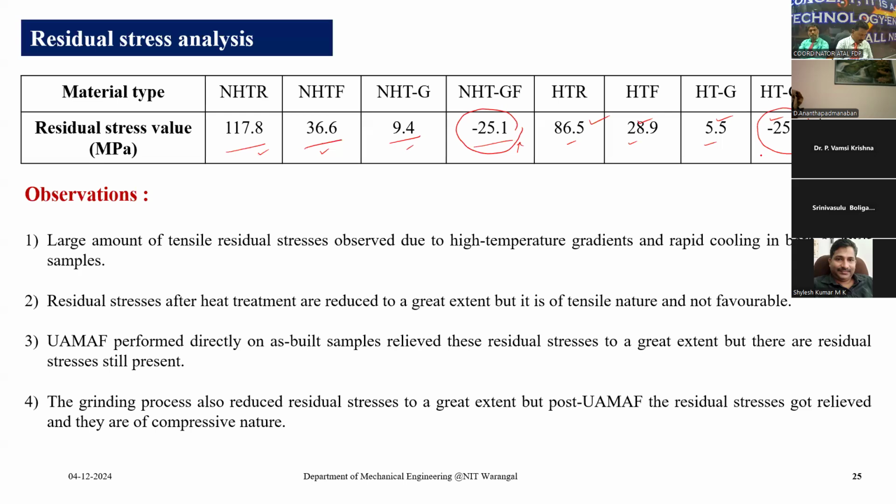Already I told you at the start itself, the tensile residual stresses observed are due to the high temperature gradients and also rapid cooling in the as-built samples, and the residual stresses after heat treatment are reduced compared to non-heat treated samples. These are reduced. However, this is still tensile in nature before the finishing process.